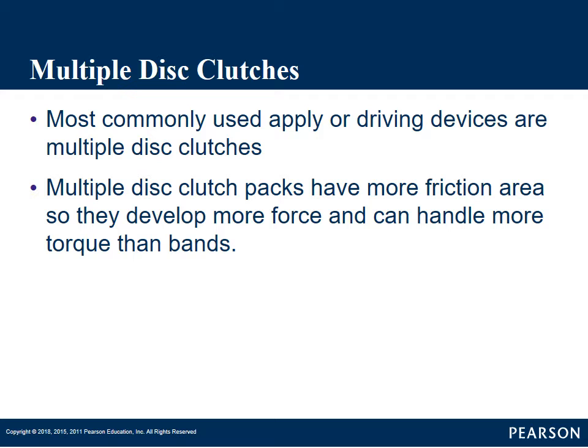They prefer those over bands because the big thing is multi-disc clutch packs have more friction area. If you remember Pascal's law, when we apply hydraulic force, the larger the area that we're applying it to, the more force we can transfer to our clutch packs.